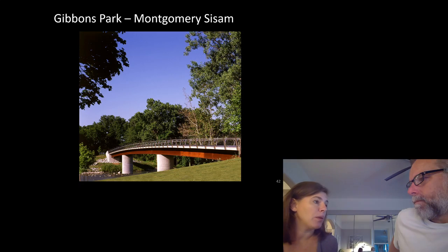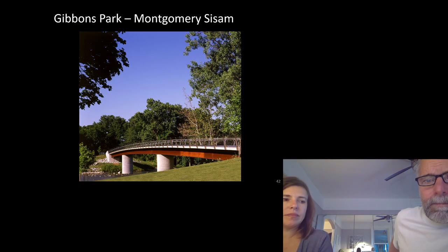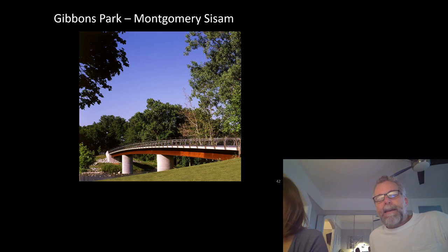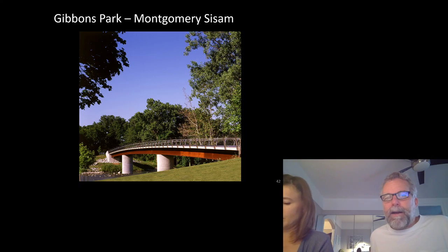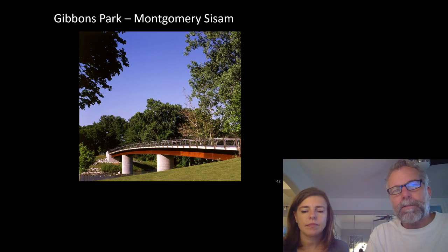And then you were talking about deflection. So yeah, if deflection and vibration are the things that control the design, which they very often are in pedestrian bridges, it is dramatically stiffer by having continuity over the supports as opposed to letting it hinge at the support.